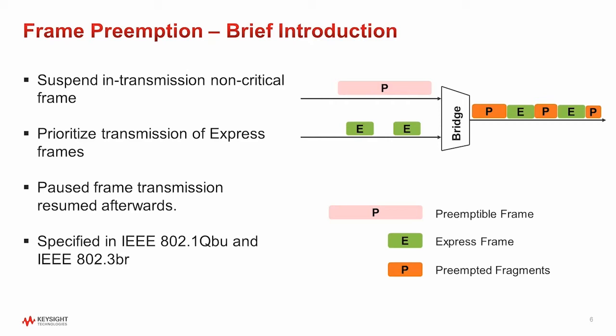Preempting non-time-critical traffic sometimes can actually result in erroneous fragment generation. In this type of implementation, which is an improper implementation, this can cause a lot of consequences, such as a switch can generate erroneous fragments, which can jeopardize the time criticality of the fronthaul network. Or maybe while preempting, the preempted frames can suffer from added overhead or inefficient reassembly implemented in the switch.